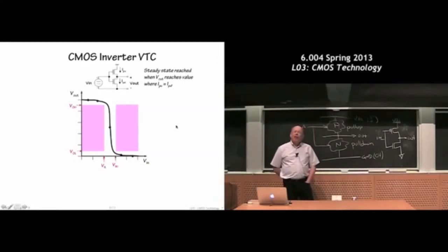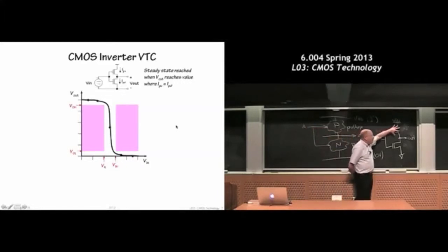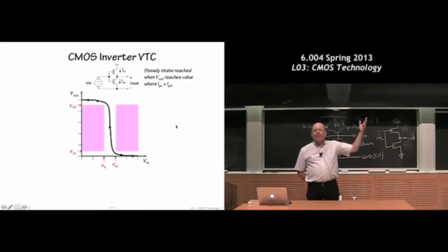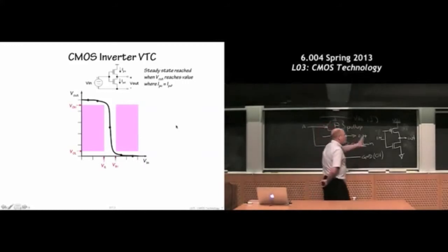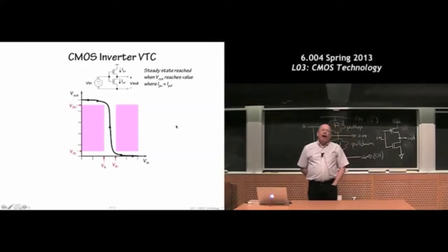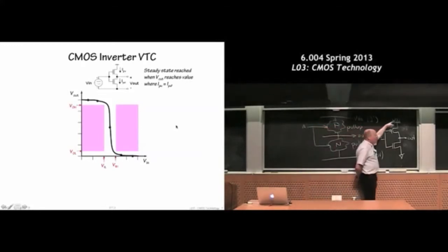What happens if they're both on? What can you tell me about the output? If I have a pull-up connection and a pull-down connection at the same time, okay, there's a couple things. One, from a logical point of view, we probably will produce some sort of voltage in the middle, which is a forbidden voltage. In other words, we don't expect a logic output from this. Okay, I'm using my battery to drive this connection.